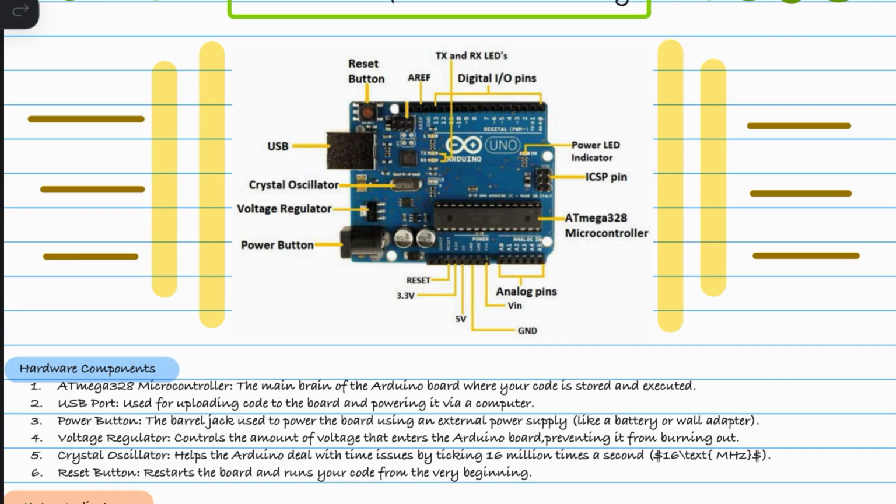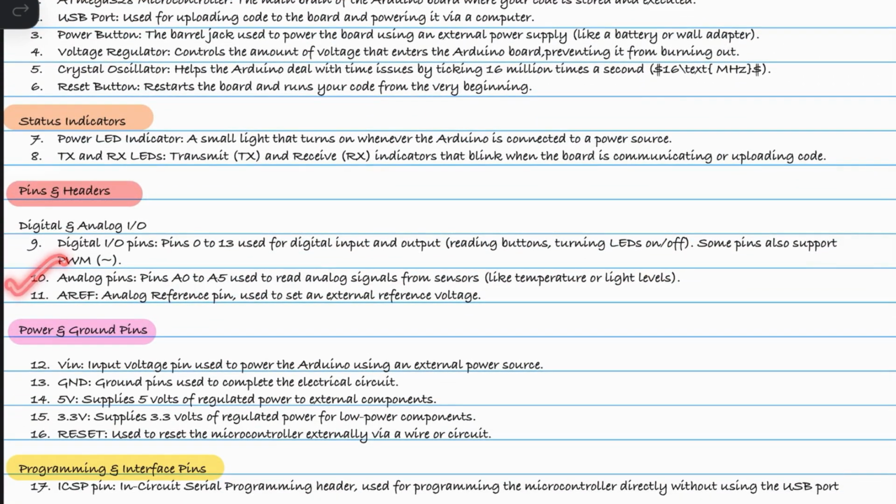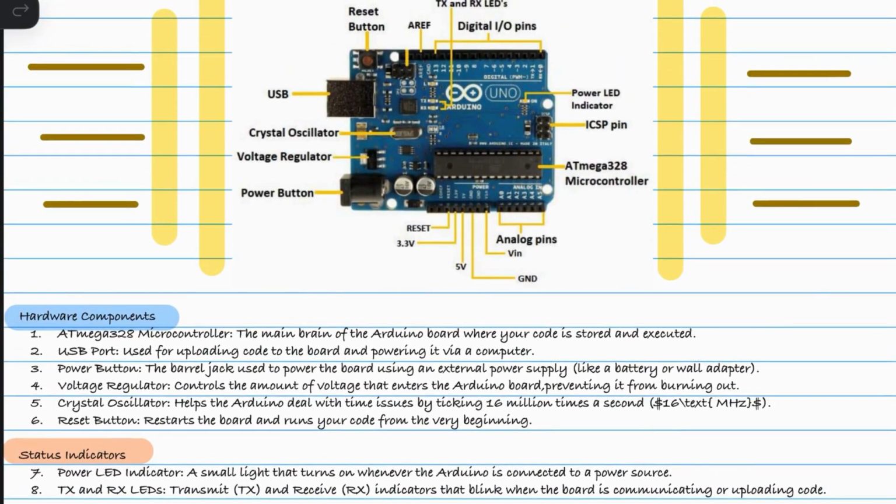Alright, and then we also have analog input pins. So analog input pins you see over here from A0 to A5, right? So these are where the real world IoT sensors like gas, temperature, or light, whatever sensors they are, are put into. So they send continuous varying voltages. So these 6 specialized pins channel the signal into the controller. All right, it sends it into the microcontroller.